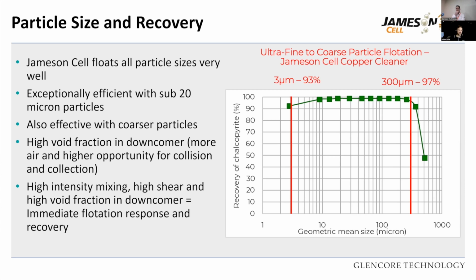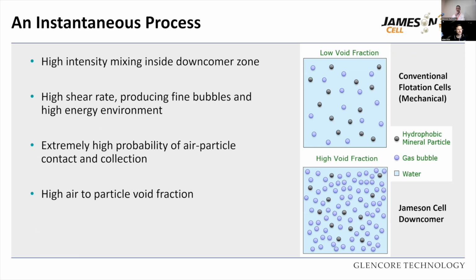And as I said, this then becomes very effective at the collection again of both fine material and coarse material, and it's that combination of the small bubbles and the high void fraction area within the downcomer. So when we talk about void fraction area, essentially what we're looking at here is how many bubbles are within basically a specific area.